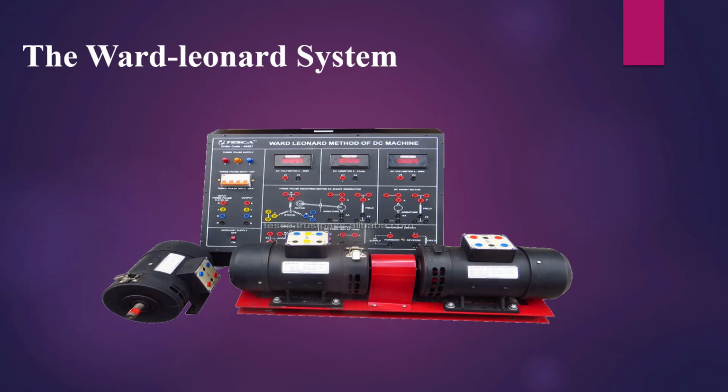Since the 1970s, the controlled DC voltage required for DC motor speed control has been more easily produced from the three-phase AC supply using a static power electronic AC or DC converter, sometimes called a controlled rectifier. Because of its low cost and low maintenance, this type of system has completely superseded the Ward-Leonard system. However, DC motors are less common now due to technology and maintenance cost.